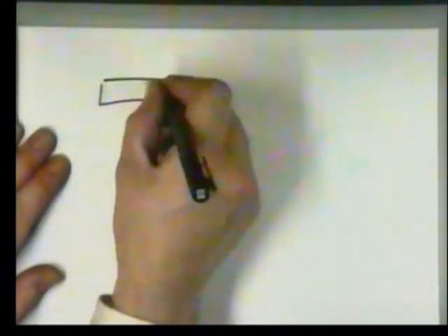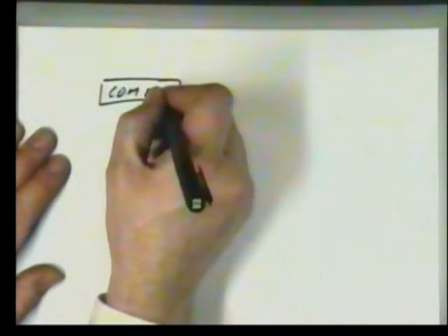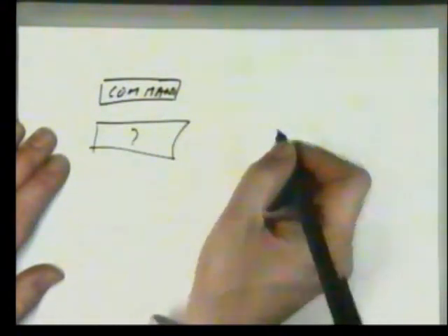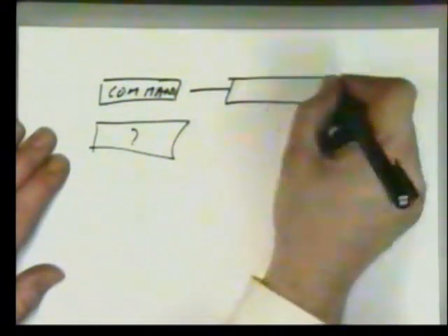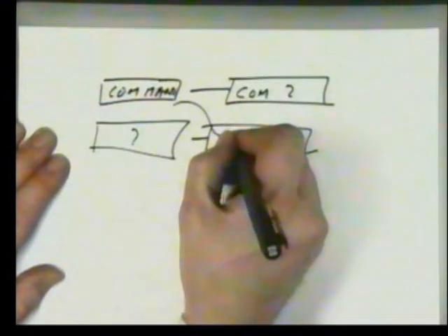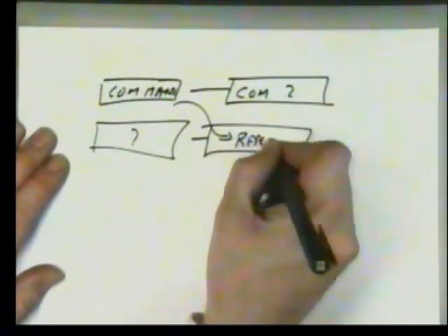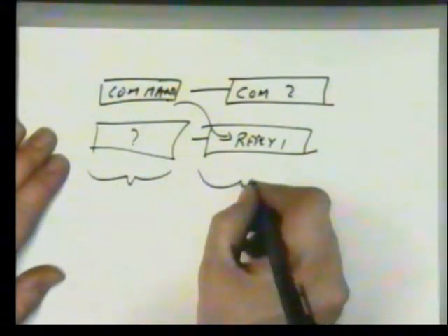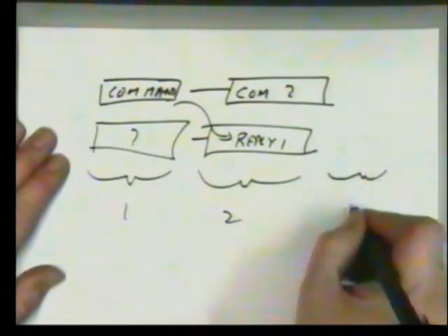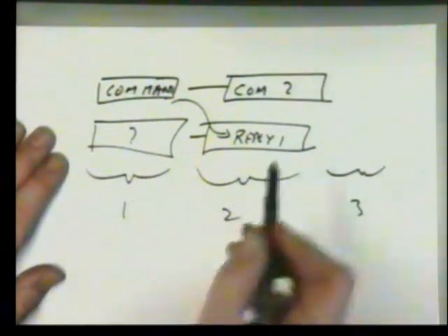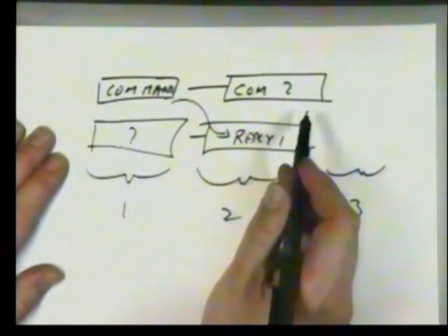So on a typical transfer, we would output a command and we would receive back garbage. On the next transmission, we'd output command number 2. But what comes back is the reply to the previous command from the previous byte. Remember, these are the byte operations. Byte 1, byte 2, byte 3, and the slave is always out of phase. It gets the command on the first transmission, then it sends its reply back on the next transmission.